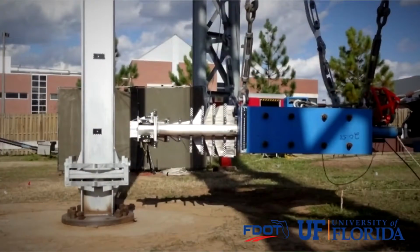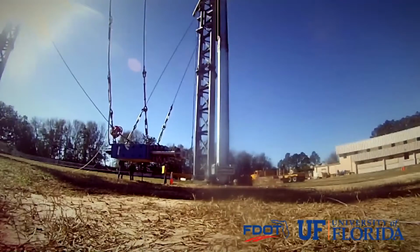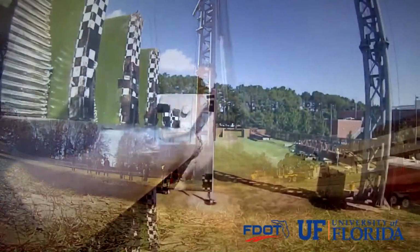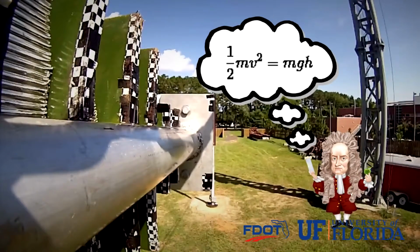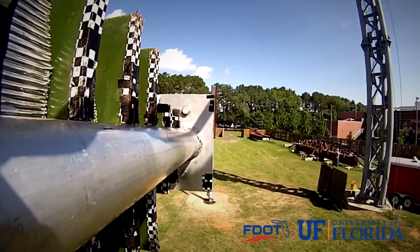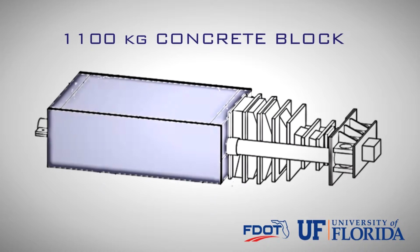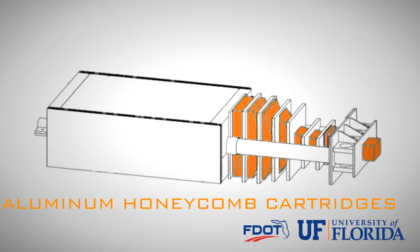For impact with the breakaway systems, the crushable nose is raised to a 12-foot drop height and released. After release, the potential energy stored in the crushable nose was converted into kinetic energy, allowing for an initial impact velocity of 19 miles per hour to be reached. The force deformation behavior of the crushable nose was controlled by an 1100 kilogram concrete mass in addition to the deformation of aluminum honeycomb cartridges shown in these compartments.